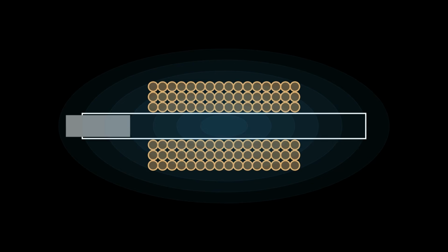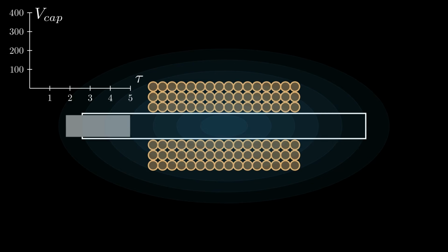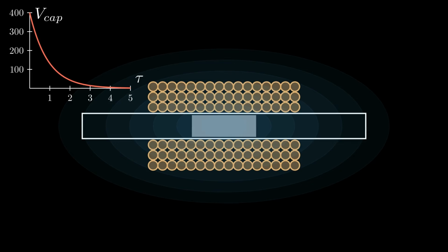When it's placed too far from the center, the magnetic field strength out at that distance is too small to apply any significant force to the projectile. And by the time the projectile reaches the center, where the magnetic field is the strongest, the current flow will be at a minimum as the capacitor bank will be significantly discharged by that point.